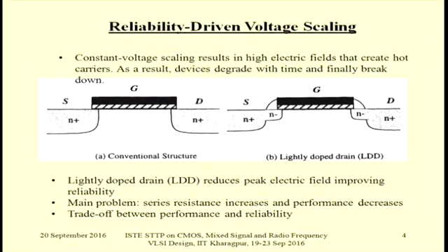It can lead to lower transconductance. Then, particularly more important is the development of hot carriers. These hot carriers can lead to eventual breakdown if they are left unchecked. That involves random propagation of the electrons and holes, carriers. And heating effect, all these are unavoidable if you apply constant voltage scaling and the field is allowed to increase. So the device degrades with time and finally it can break down. There is a certain possibility.